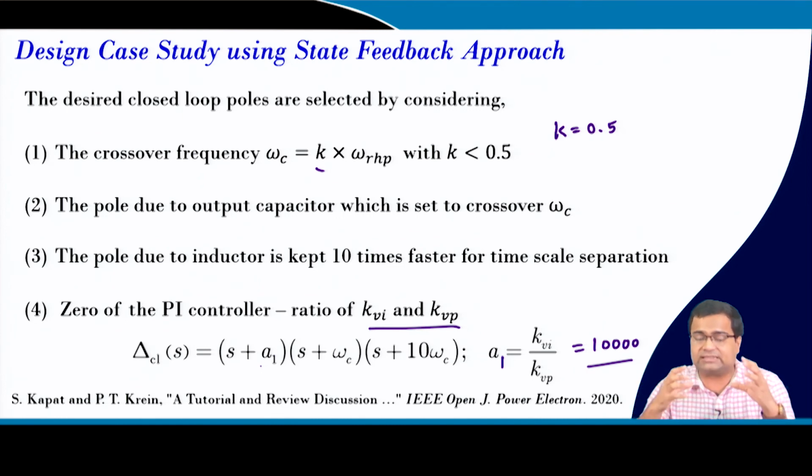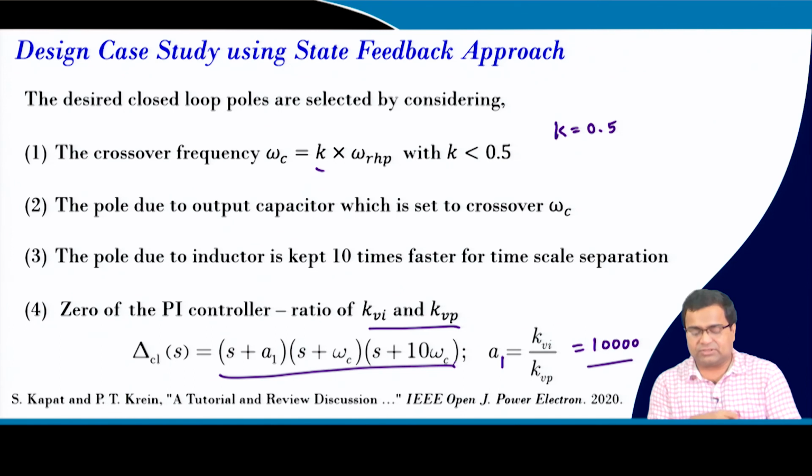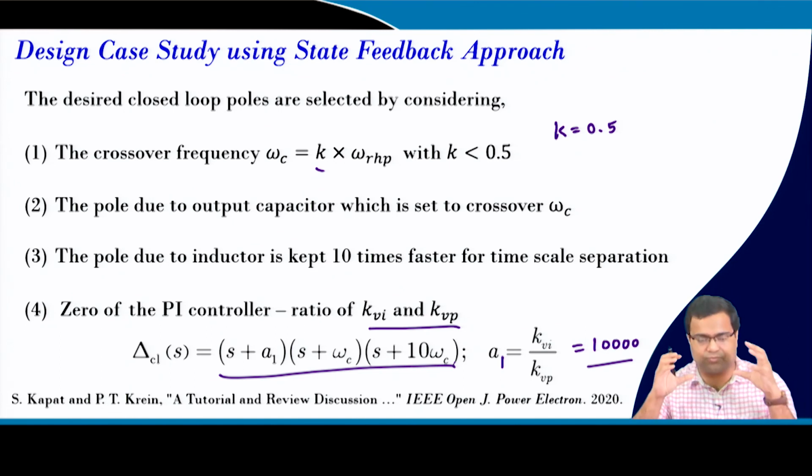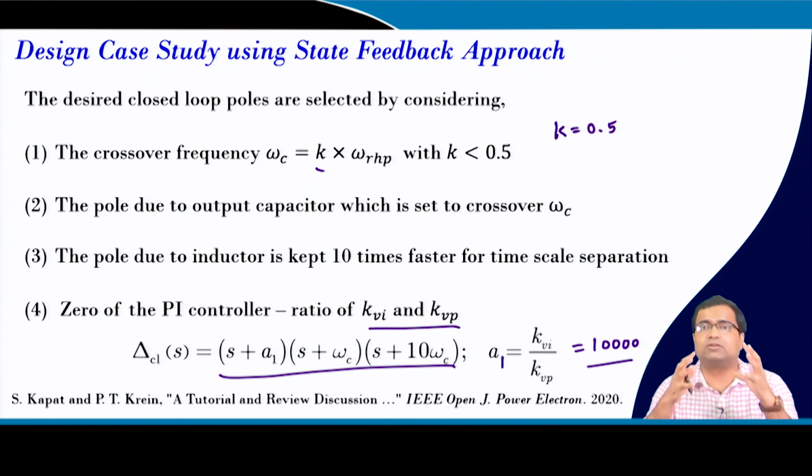And of course, in this approach we are taking all these 3 poles into consideration. That means in the earlier case there was a pole-zero cancellation, but now it is not there. So, the whole system is perfectly controllable. Now, we can use optimal criteria, not only for performance improvement; we can set some optimal criteria like LQR, criteria for certain cost function optimization. That kind of criteria we can use.